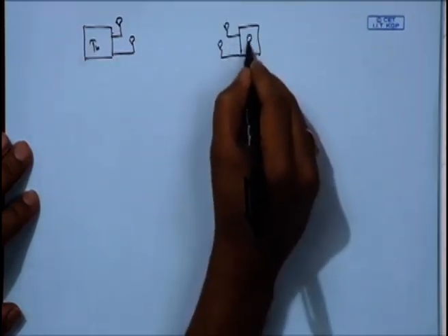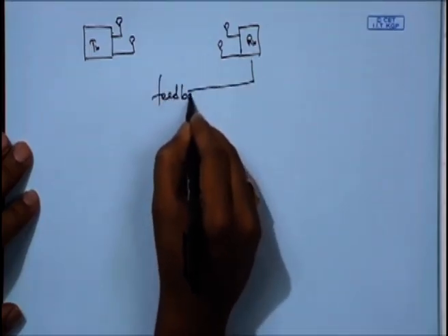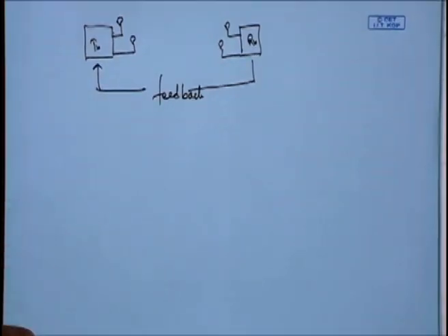Tx and Rx. So basically here there is a feedback, and if we would remember, the result of capacity in this case told us that we have the feedback about the channel state information. So we can get the eigenvalues. Once we get the eigenvalues of H Hermitian H, we are getting indication of the channel strength of the parallel modes that we can send. So based on that, again we will be distributing the amount of power which is proportional to the eigenvalue of that particular mode of the channel.